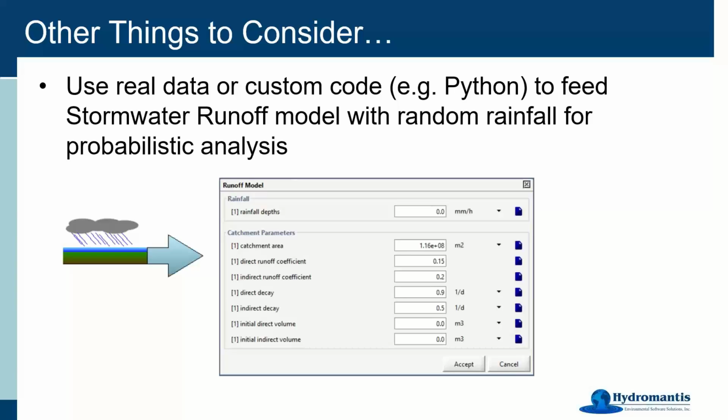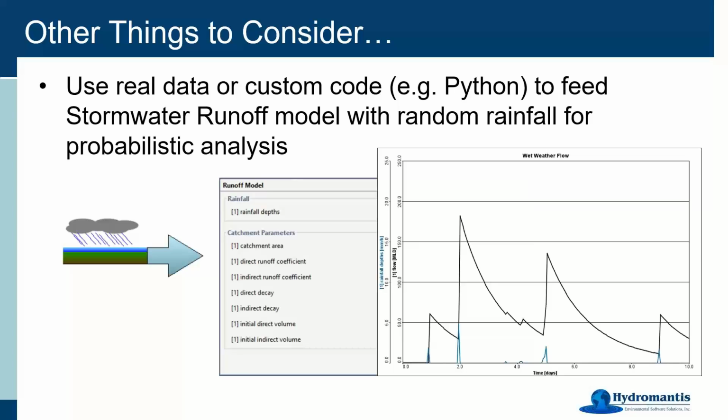We actually have this stormwater runoff influent model that you can use. It takes rainfall as an input and generates different kinds of effluent flow rates. What I've seen people use is to put your regular wastewater influent pipe, and then have this beside it and combine those two flows and feed them into the plant.